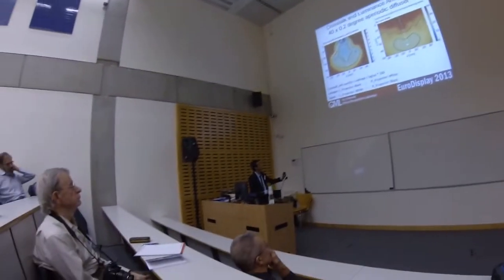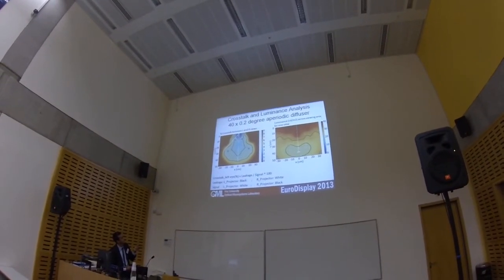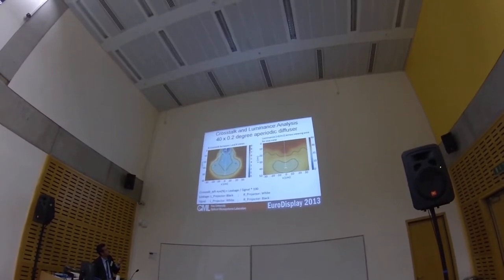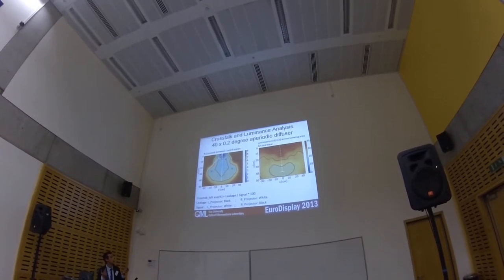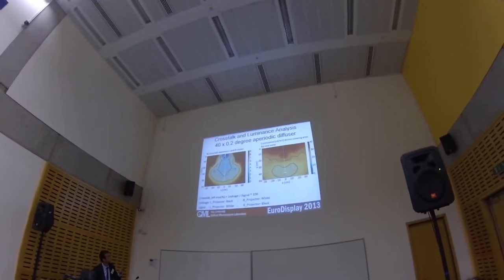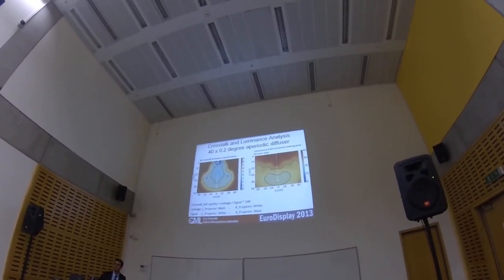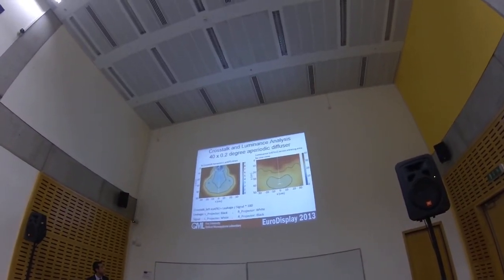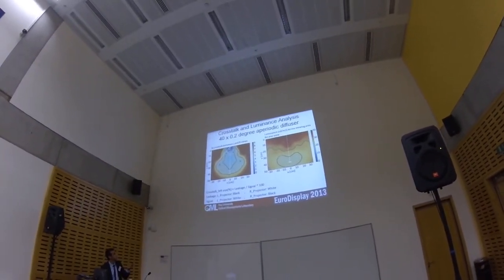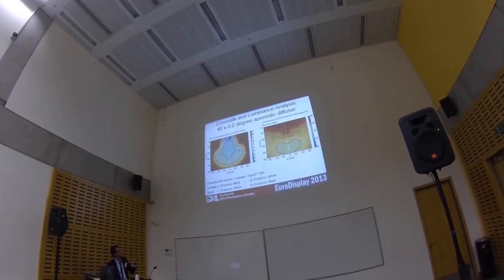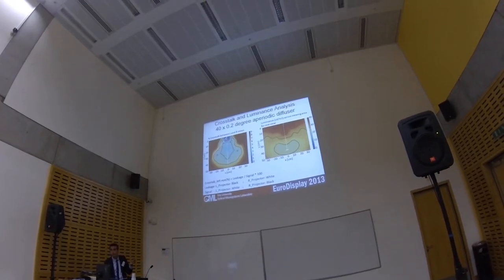As you see, the crosstalk is below 5% in this area, and this is below 4% of crosstalk, and 3% of crosstalk, and it is very low when you are really close to the projectors. The optimum crosstalk value is of course 0, but under 5% is acceptable, as the literature says. For the acceptable value, we have almost a 50 centimeter by 50 centimeter weaving area.